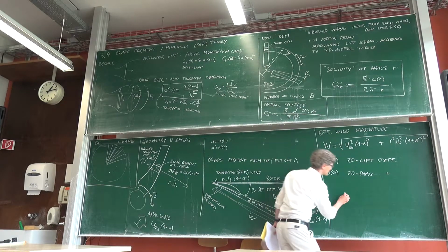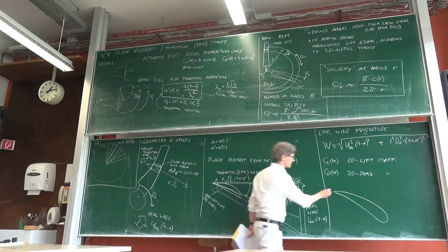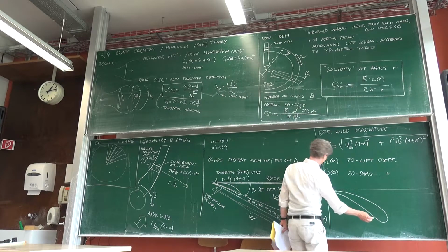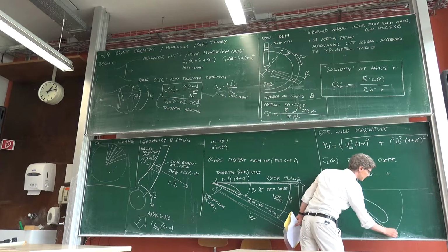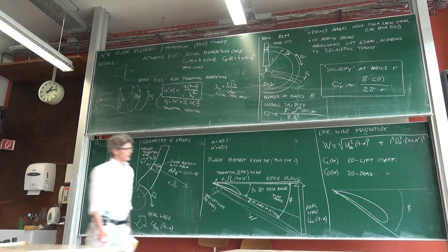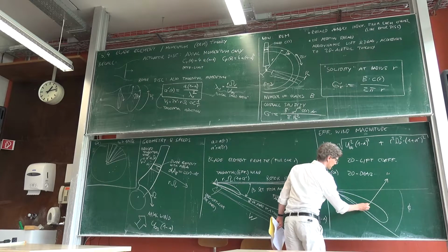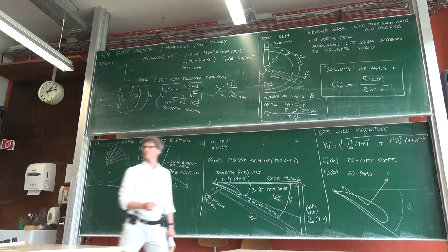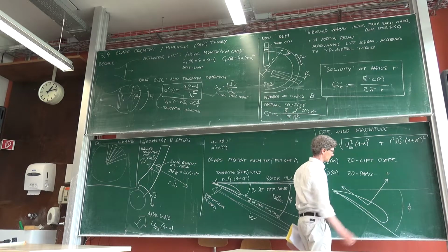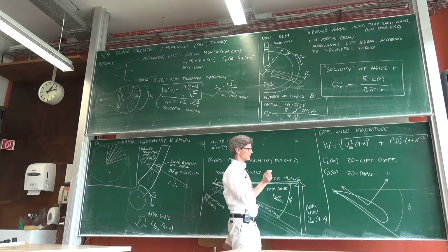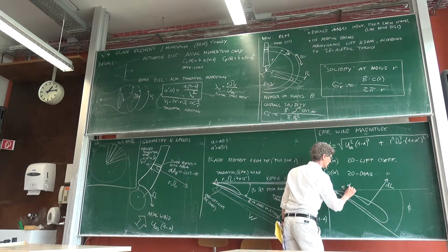What I will draw now is actually the picture again, as I said. So I will have my airfoil here, maybe like this. I have still my rotor plane here. But now I have my angle that I just defined before, I mean this, the effective wind angle, and here's my angle phi. And then I will have a lift which is in this direction, right? And I will have a drag in this direction. By the usual definitions of lift and drag, lift is always orthogonal to the wind and drag in the other direction. And because this is just a blade element, I will call it not L but DL, for the infinitesimal lift. And this is DD.